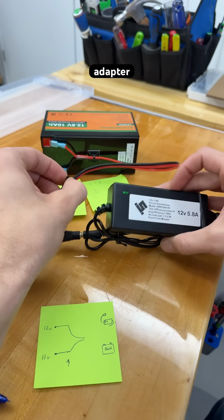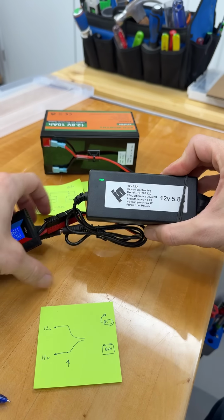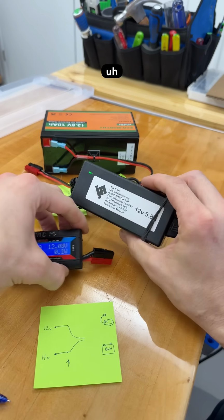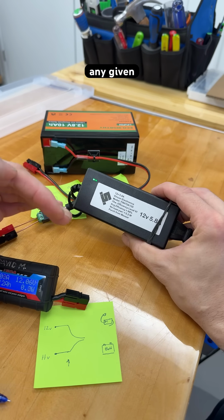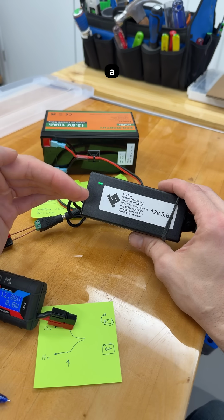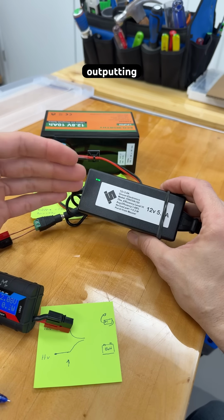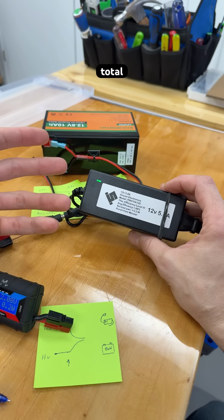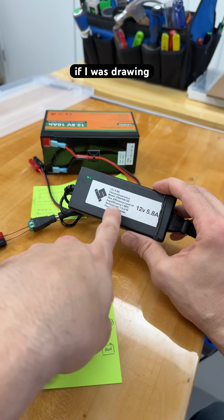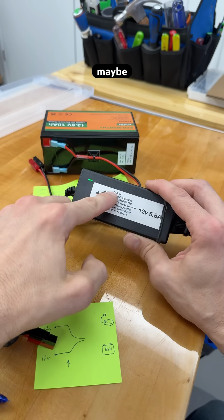And then this adapter has its own limitations, and even though it's rated for 12 volts or maybe 12.19 when we're disconnected, it has limited power at any given voltage output. So when the voltage drops down a little bit, that's an indicator that this thing is outputting part of its total limit. The limit is somewhere around 5.8 amps. If I was drawing a full 6 amps here, then the voltage would be way down, maybe near 11 volts.